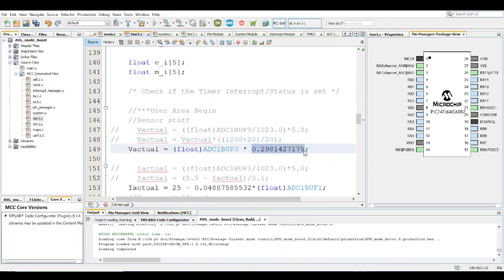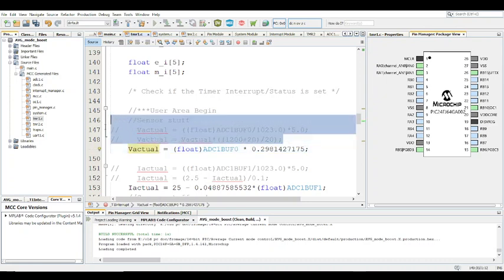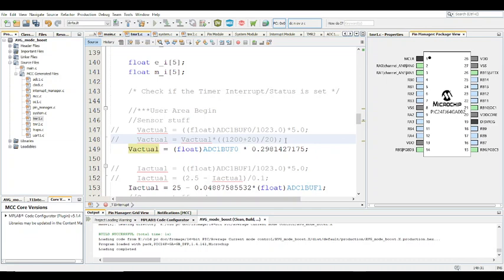I'm not including these two lines here, obviously, for the microcontroller to be quicker in calculating, so we just use a single one. But it's put here for the comments, to be modified based on your resistor value. So obviously the top resistor 1200K is going to be this value right here. The small resistor 20K is going to be this value right here. Obviously didn't write 20,000 because of space, I guess. So it just says 1200, 20, same. So that's what these two lines are for, and this is what you get in the end.